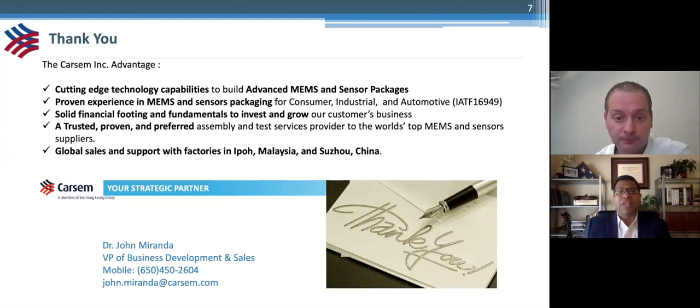This is an area where you really want to talk to your wafer fab and your provider, and understand what they're offering in terms of TSVs and stacking these PMUTs onto ASICs. I want to apologize: we can't cover everything in 7 minutes, but wafer level packaging is being used extensively here in PMUT packages.